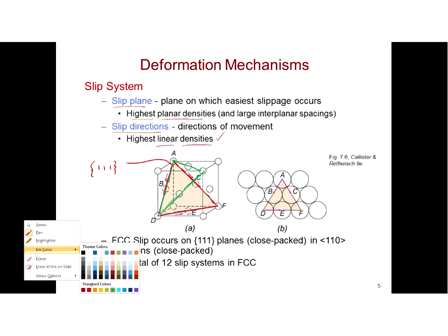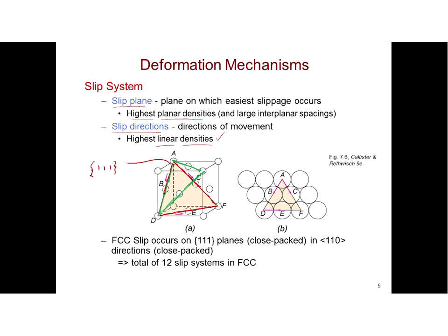All right, so that family of planes, just to remind ourselves, is the 111 plane. So this is the 111, the 1 minus 1 minus 1, the minus 1 minus 1 1, and the 1 minus 1 1 minus 1. If you were to draw all of the planes that have all the versions within this unit cell that have that same configuration and are part of the same family, and thus have the same planar density, these would be all of them.